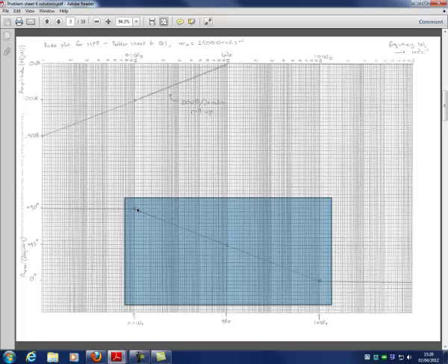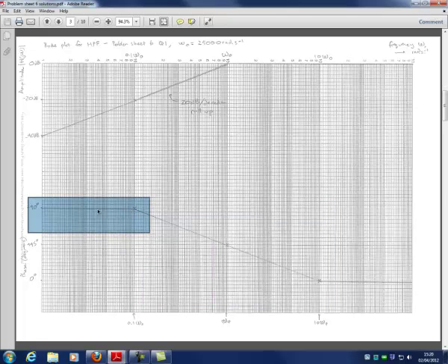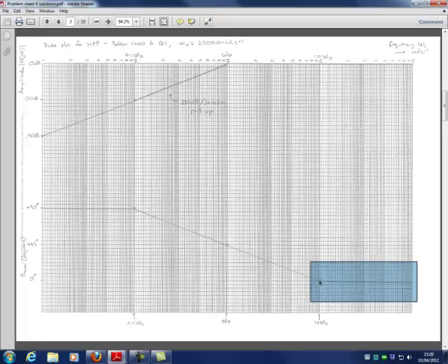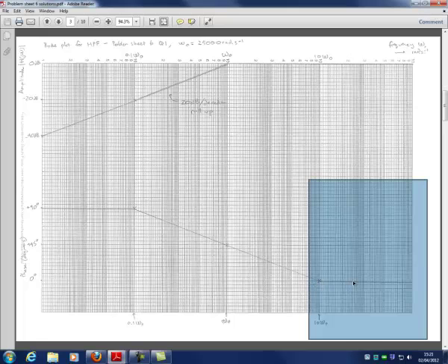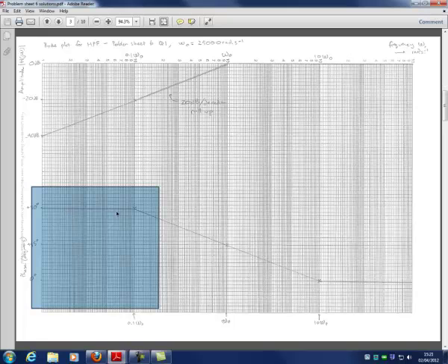So that leaves you with a sloping line. To finish off the graph, you need to extend backwards at low frequency values and upwards at the high frequency values. So these are flat. This is the transition zone here, and everything outside of it's going to be flat. So what this means is that high frequencies have 0 phase shift applied to them, and low frequencies have plus 90 degrees phase shift applied to them. And that's how you answer question 1.